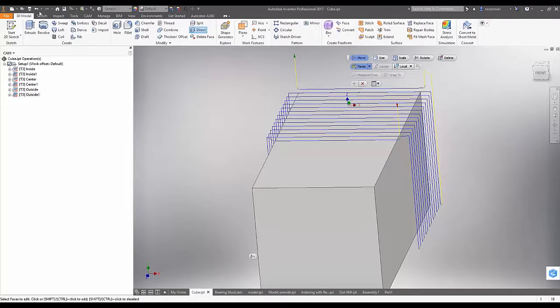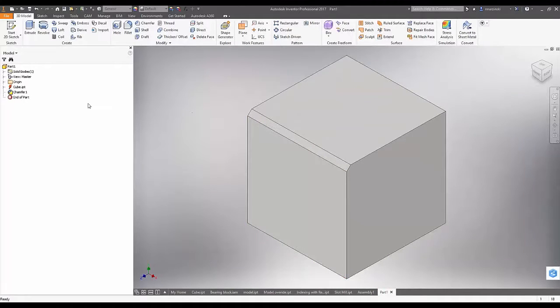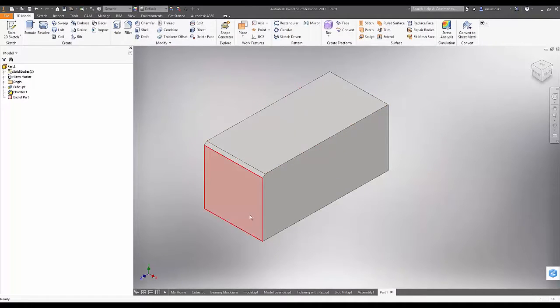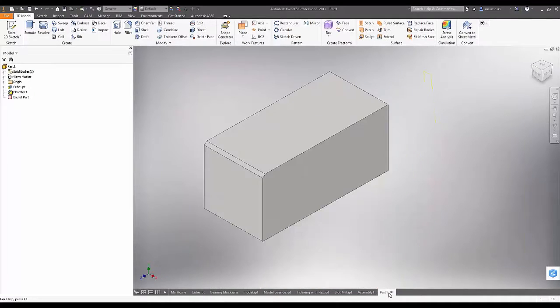So the engineer makes a change to the model and saves that. When you go to that derived part that we just created, we get an update lightning bolt here. All you have to do is click the lightning bolt. That model updates to the original. However, you're never going to affect where it came from. So that's a pretty powerful tool right there.